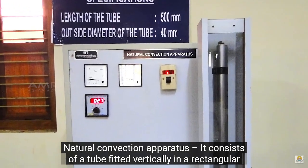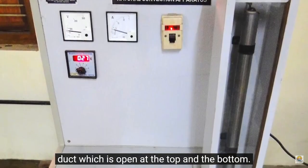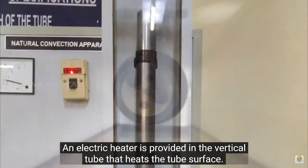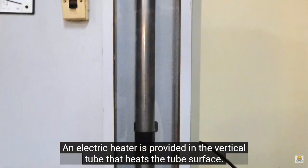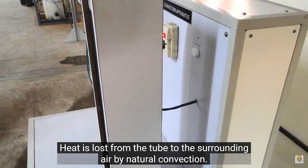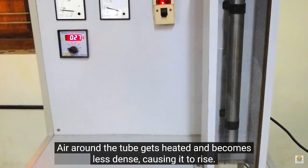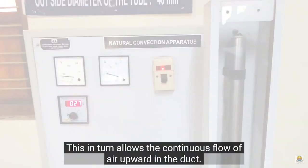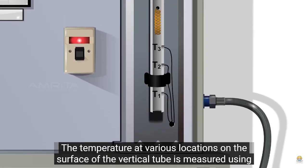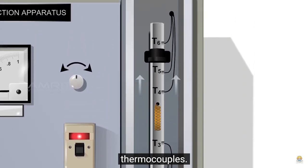It consists of a tube fitted vertically in a rectangular duct which is open at the top and the bottom. An electric heater is provided in the vertical tube that heats the tube surface. Heat is lost from the tube to the surrounding air by natural convection. Air around the tube gets heated and becomes less dense, causing it to rise. This in turn allows the continuous flow of air upward in the duct. The temperature at various locations on the surface of the vertical tube is measured using thermocouples.